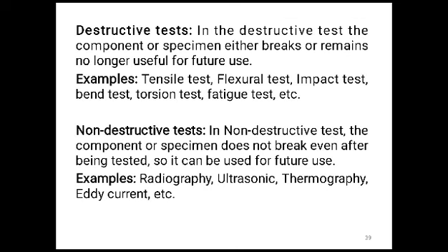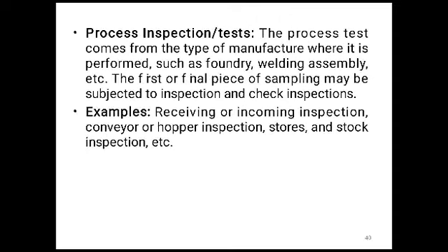In the destructive test, the component or specimen either breaks or is no longer useful for further use. Examples: tensile test, flexural test, impact test, bend test, torsion test, fatigue test, etc. In the non-destructive test, the component or specimen does not break even after being tested, so it can be used for future use. Radiography, ultrasonic, thermography, eddy current, etc.